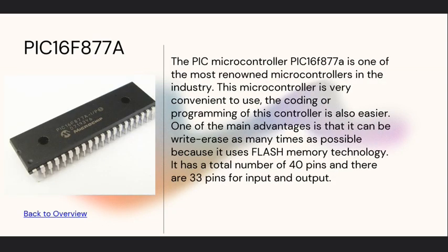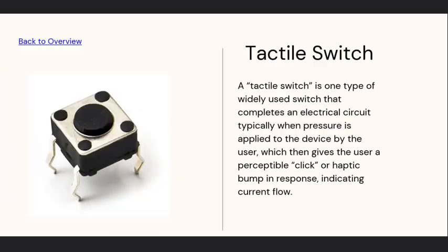The PIC microcontroller. PIC16F877A is the microcontroller that we have used for our project. It is one of the most renowned microcontrollers in the industry. It is very convenient to use, and the programming is also easier. One of the main advantages is that it can be written and erased as many times as possible because it uses flash memory technology. It has a total of 40 pins, and 33 pins are for input and output.